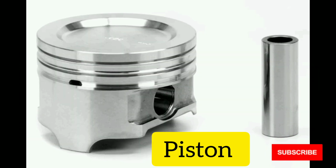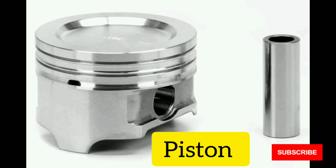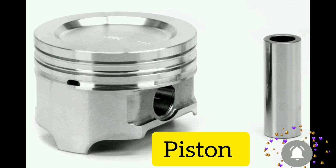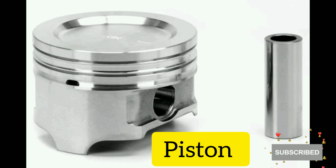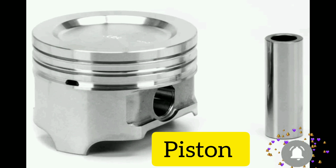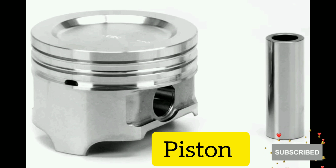This is a piston of an internal combustion engine, and it's located in the cylinder block, and it has many purposes in a four-stroke engine. It provides the moving seal of the combustion chamber against the crankcase and oil pan, and it absorbs the pressure of gas generated during the combustion process and transmits that pressure force to the crankshaft via a connecting rod.